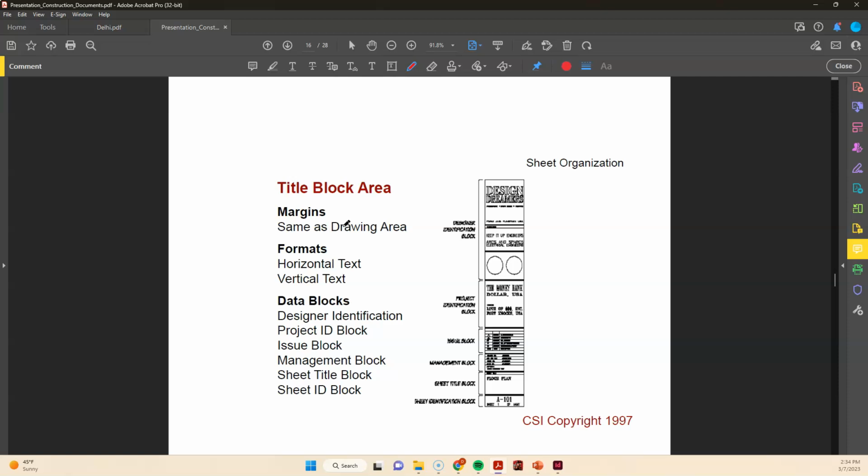Okay, title blocks, very important. I'm not going to delve into this too deeply. I'm going to have to be kind of quick about it. So in general, yes, they could be horizontal, running across the bottom. They could be vertical, running here. They contain a lot of important information. It's really a whole lesson just on how to manage your title block, kind of. Some information on the title block is project specific, or project wide, and some is sheet specific. So it's important to understand that.